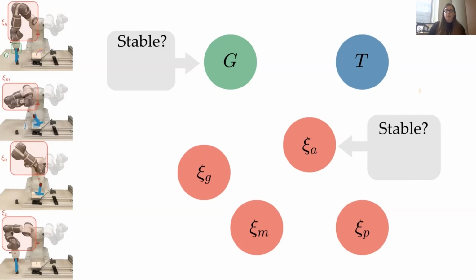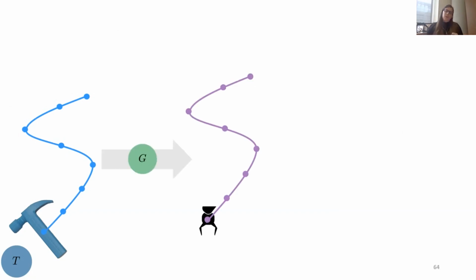And so the way that we quantify this is that as a function of where we place our tool relative to, in this case, our nail, we have a series of waypoints defined specifically in task space that define the motion that we want to achieve. Again, for the hammering task, you can imagine it's kind of this arcing motion. Given our grasp relation, we can transform the path from our tool into a path of our end effector.